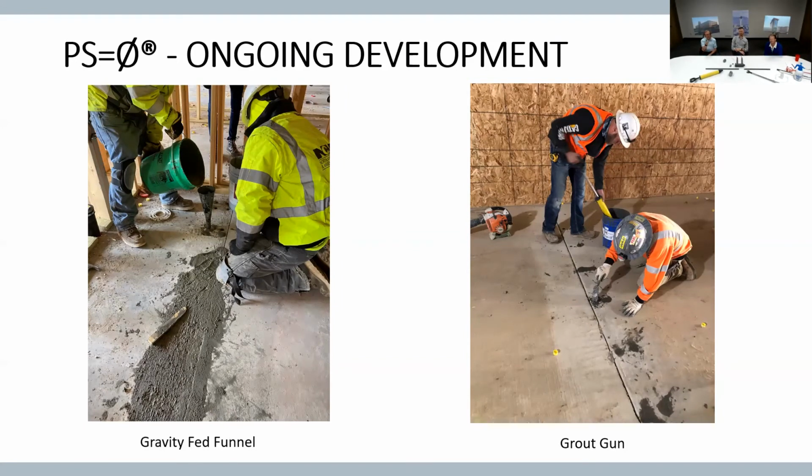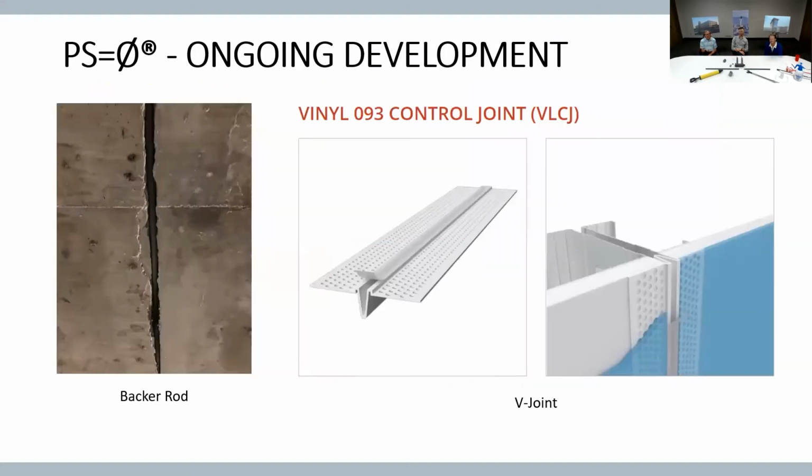And if you like to keep the joint on top really clean, there can be a masking tape type thing or duct tape, like you'd mask for painting. We used to use the funnel for gravity feed, but these pumps work much better for us. And this is the sheetrock. It's sort of upside down, how we would use it, but that's what we intend to use instead of the backer rod. That has to be installed after the fact, and when it's 15 or 20 feet in the air, it's kind of difficult.